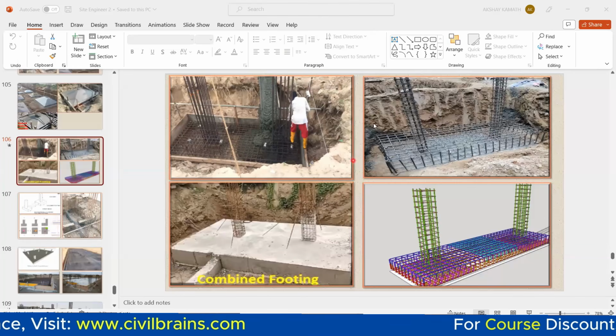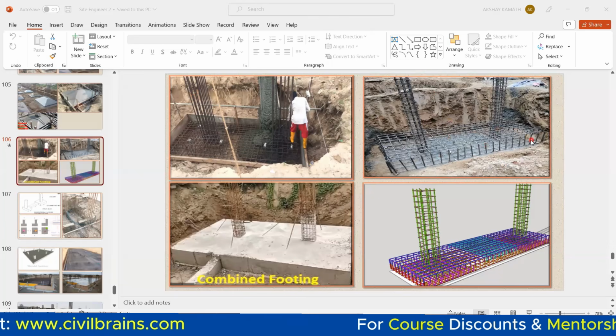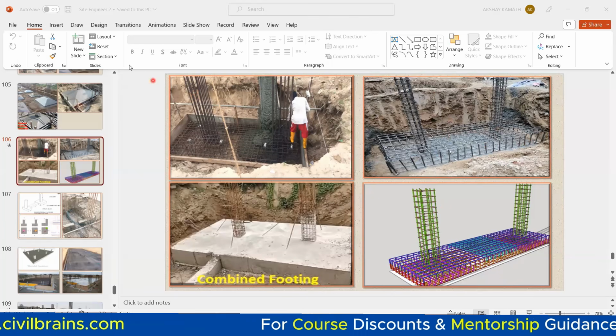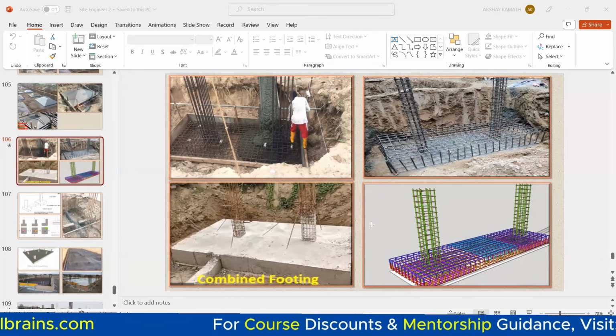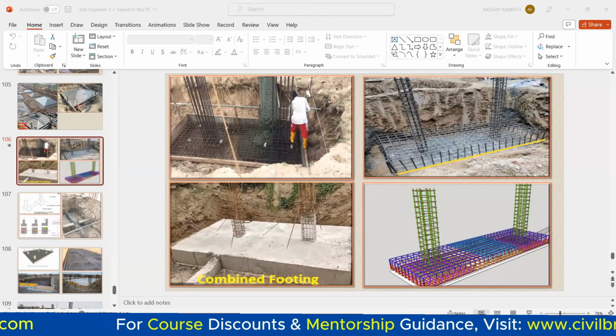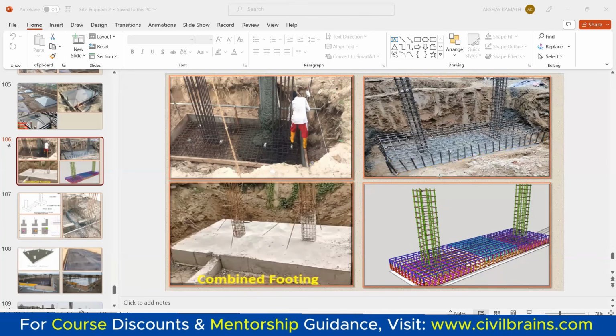So in this lecture, we'll try to see how to take out the quantities for the combined footing. That is a BBS for a combined footing. Now, one thing you need to understand in the combined footing: in the isolated footing, we used to have a bottom mesh, that is, a bar on the longer span and a bar on the shorter span. This was the isolated footing, isn't it? But in case of combined footing, what will happen?